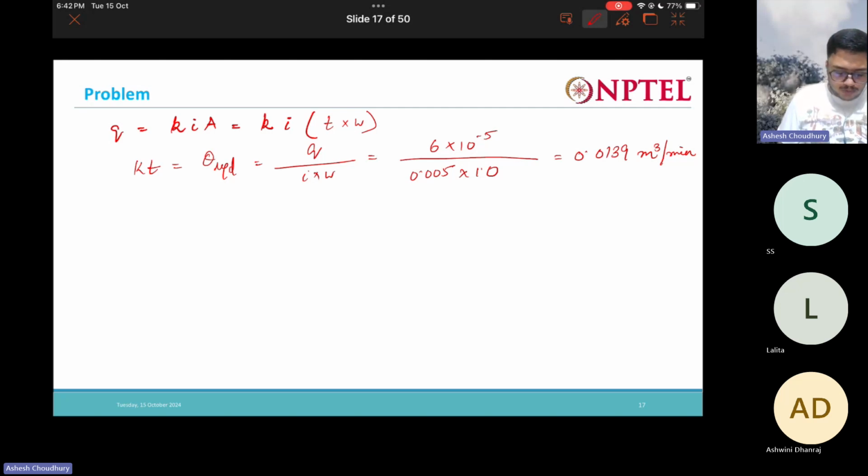Now we need to get the theta of the geocomposite or geonet that you are using. If you recall from the previous class, we had theta on one axis and vertical pressure on the other, with graphs for various I values, the gradient values.